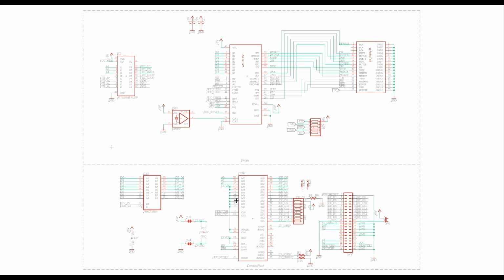And then down here we have the compact flash. Compact flash is super simple to interface to an 8-bit retro computer. I used a buffer here. It takes those ID0 through ID7, those I/O data bits, as well as a direction and a chip select, and it buffers them onto D0 through D7 on the I/O connector for the compact flash. Technically, you don't even need this data buffer. I've seen many implementations where they won't buffer it, but I think some compact flash devices are less stable when you stick them directly on a bus, so this helps.